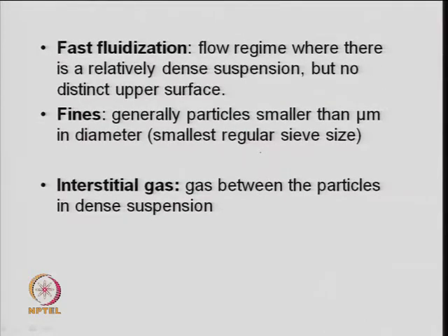Then fast fluidization. This is a flow regime where there is a relatively dense suspension, but no distinct upper phase. As I said when I was showing the picture of different types of fluidization, at high superficial gas velocity, the bubbling fluidized bed first transforms to a turbulent fluidized bed, and then you have a fast fluidized bed. So, basically this is at higher gas velocity.